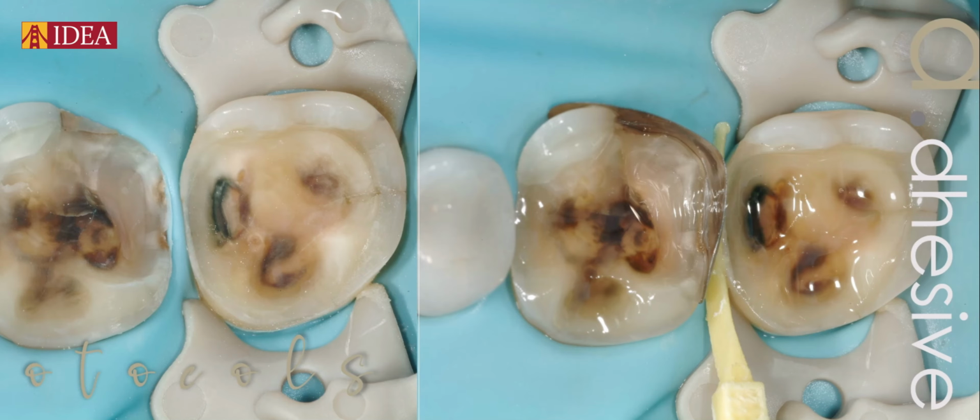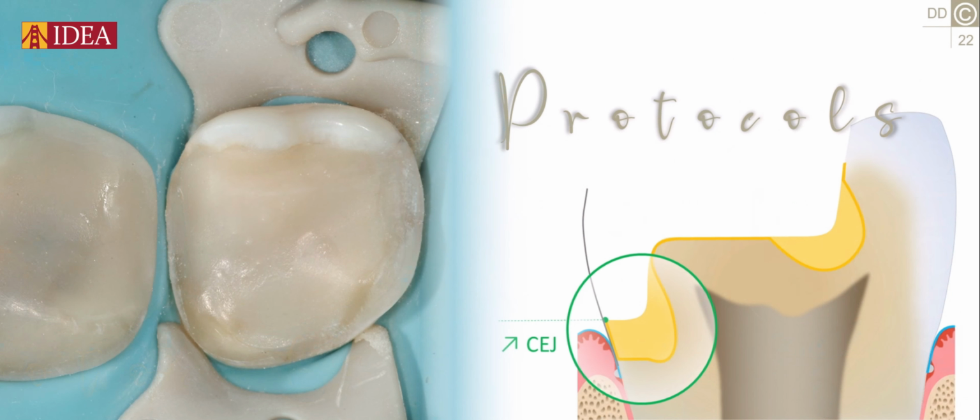It's something that I personally don't like to treat with composite because composite has less potential to block diverging forces. Even if you include fibers, fibers will strengthen the composite, slightly increase the stiffness of the composite, but will not have much effect on blocking diverging forces, which will unfortunately lead to progression of the cracks.